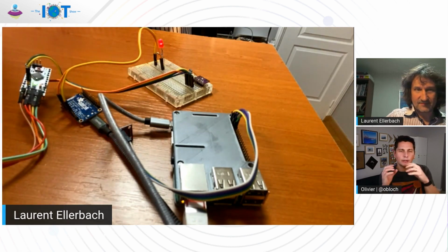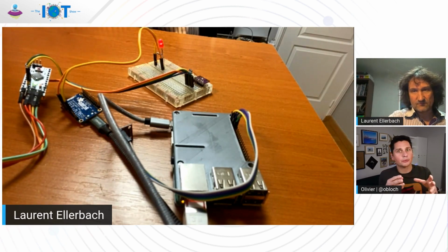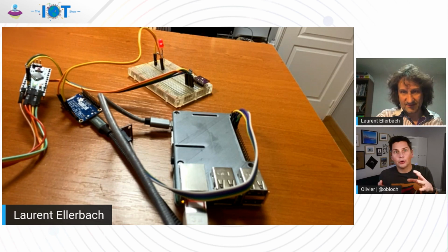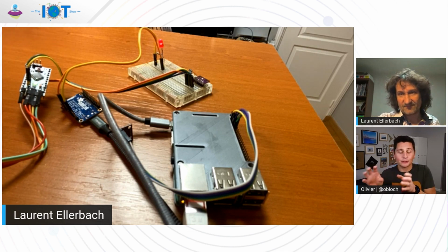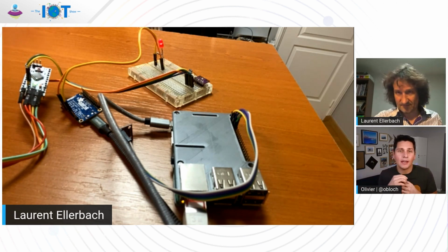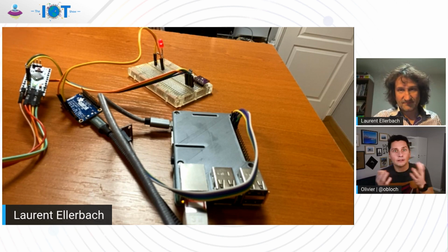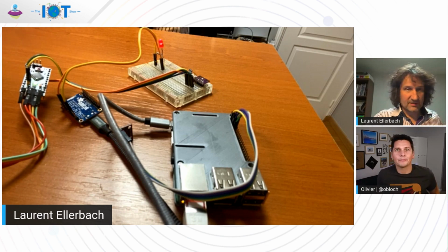So in a nutshell, nanoFramework for microcontrollers, the tiny version, does include access to the hardware, and also has an SDK for accessing the cloud, right? Connecting to Azure IoT. And on the bigger side of things, big .NET, you add the .NET IoT library to access the hardware, and eventually you have the device SDK, the C# one, for connecting to Azure IoT as well. So you do the same things on different sizes of devices, leveraging the bigger framework on the bigger device, obviously. Absolutely.